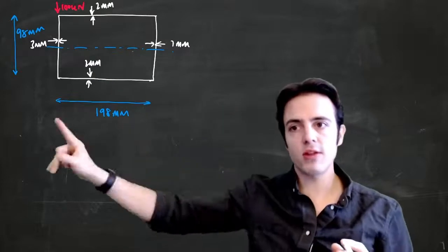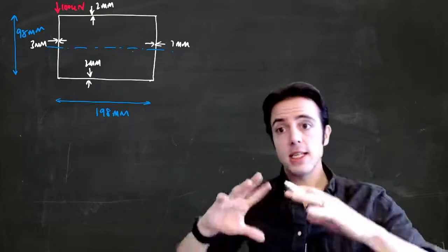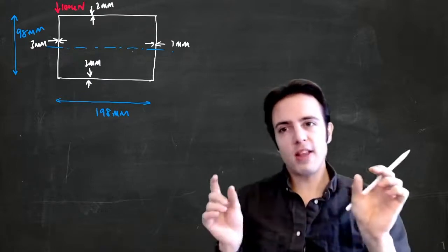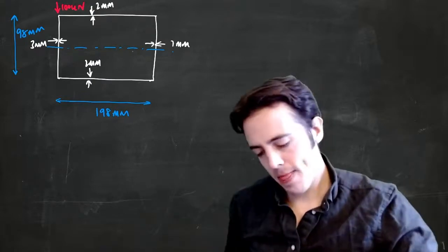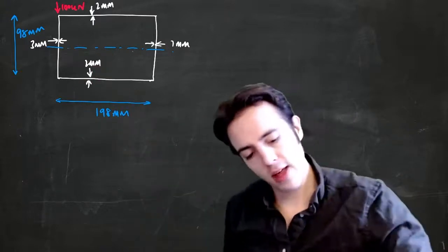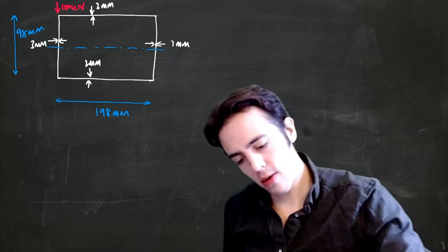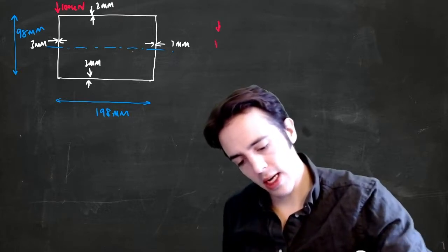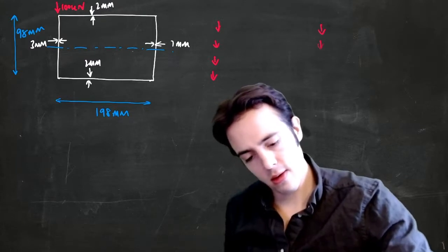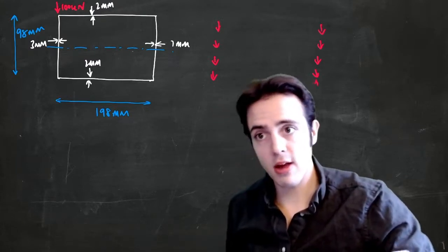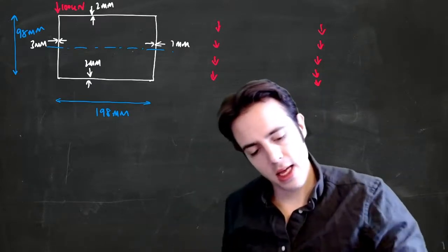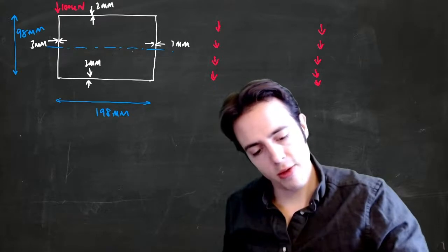So we've drawn to the centroid. We no longer have to think about the shape of the object, or rather we don't have to think about drawing the thickness of the object. So because we've got this applied load here, we spoke about the direction of how these shear flows have to work. We know that the two vertical members will have shear flows in these directions, two shear flows going down, and then let's draw my object in the background here.